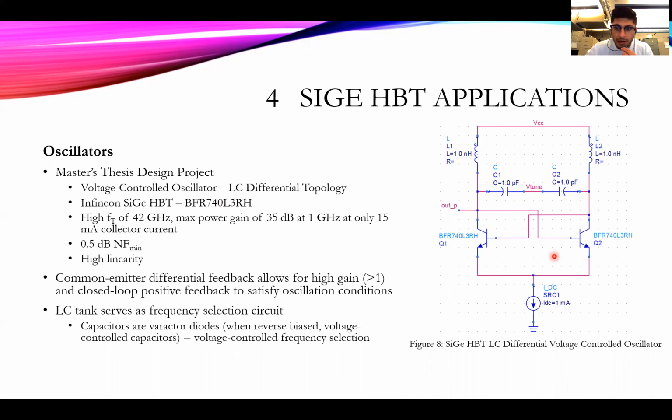I wanted to summarize what I've highlighted here, and some key takeaways are the SiGe HBT features, as we've mentioned: the emitter-base is the heterostructure, where the base is the SiGe component and the emitter is the actual silicon component itself. The base features uniformly graded doping, which is highly doped, and that allows us to decrease the ohmic resistance and increase our base electron transport, which, as we know, decreases noise generation as well as increases gain.